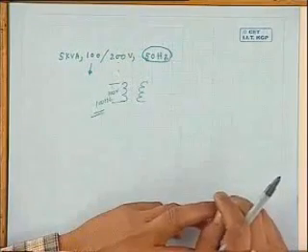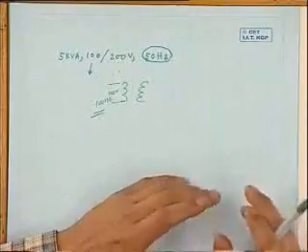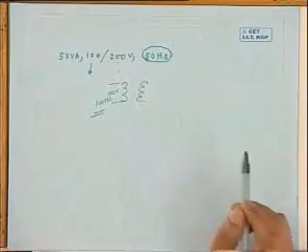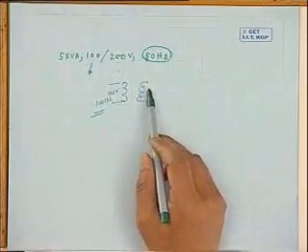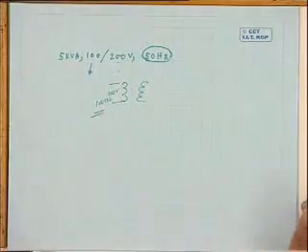Suppose open circuit. The induced RMS voltage magnitude will be 200. Is it not? RMS voltage magnitude does not depend upon frequency. Secondary induced voltage frequency will be 100 hertz. Are you getting? It will be 200 volt, 100 hertz.